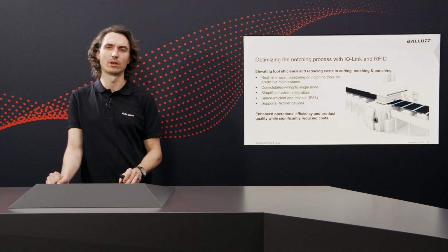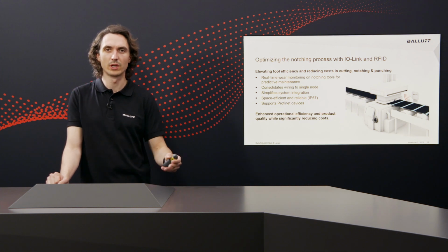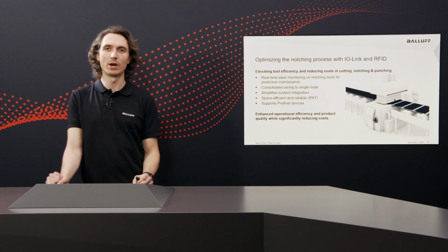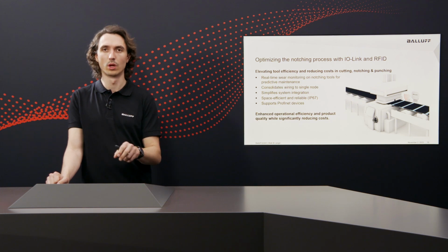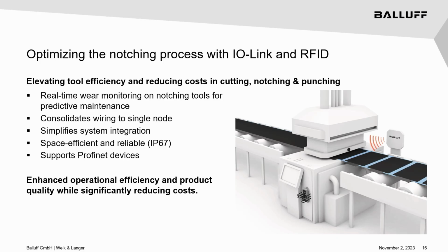And it might sound like a lot, but in fact, because this is really a high-speed machine, you have to resharpen that notching tool every, let's say, 2 or 3 days. And this is why it's even more important to apply technology like IO-Link and also RFID to, first of all, not just ensure that the right tool is used for the right product variant, of course, that's quite clear, but also to ensure that because of the data flow you generate this way, you are well aware of any